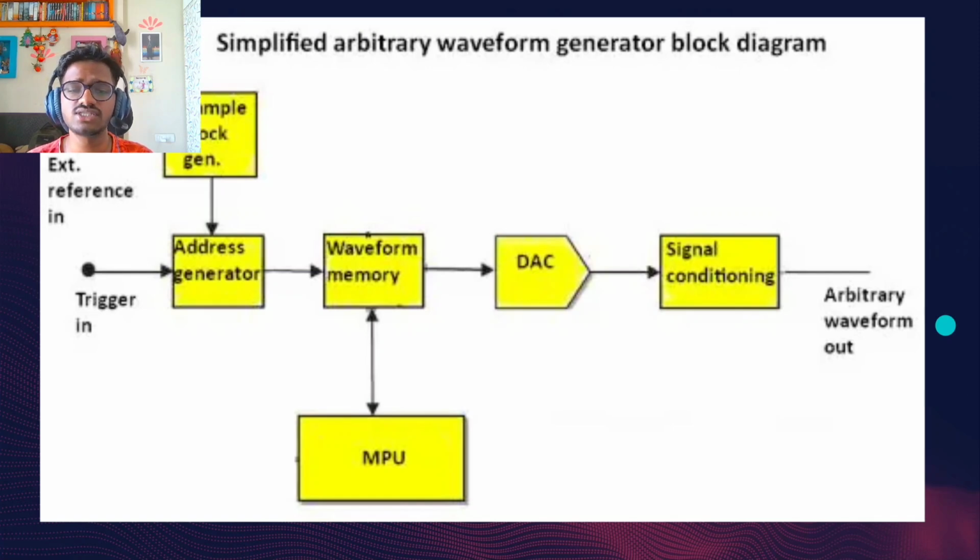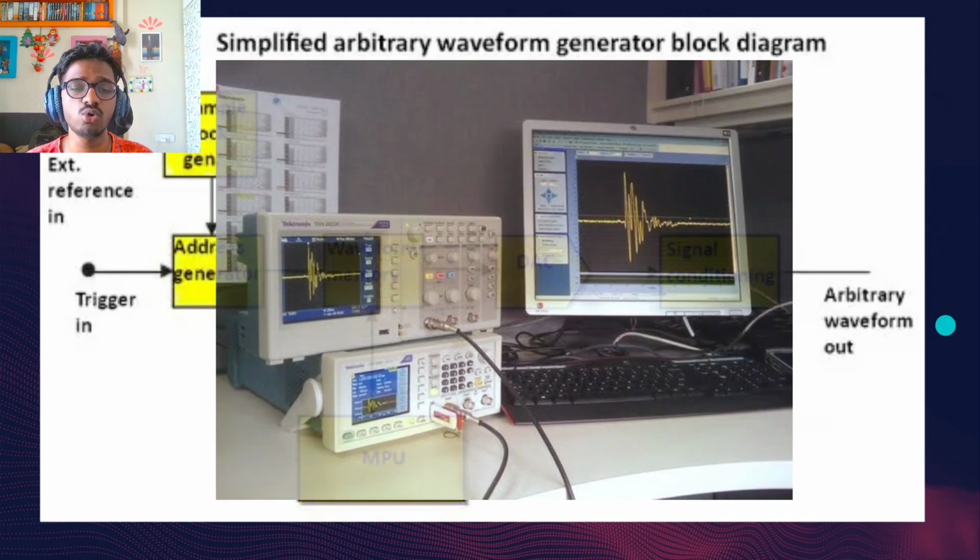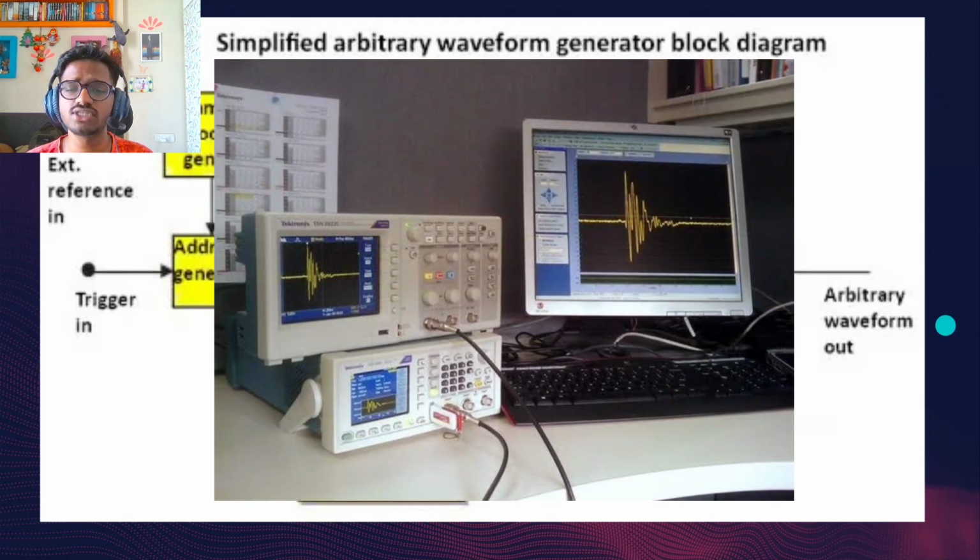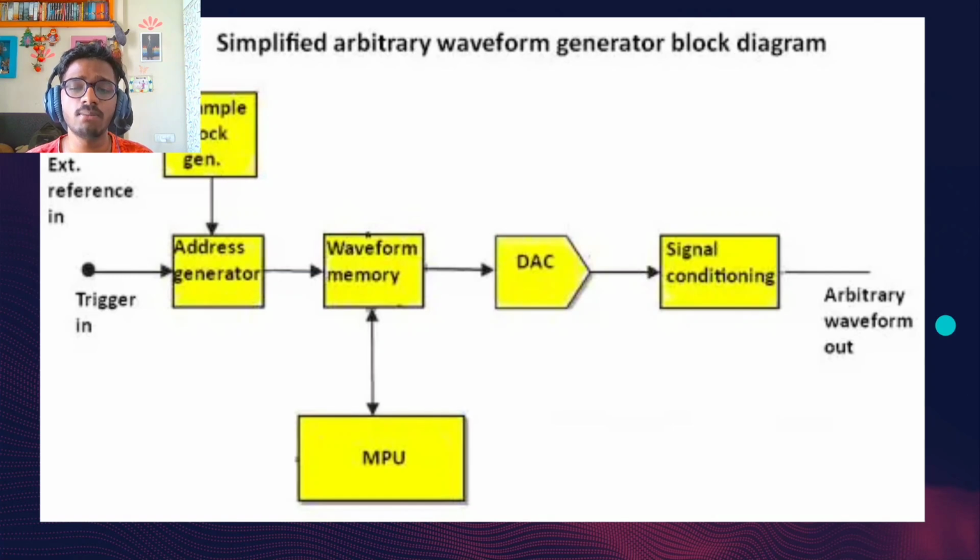While MATLAB and signal processing toolbox are common for signal generation, AFGs now feature a plugin architecture for easier waveform creation. These plugins, integrated into the AFG's GUI or run on a PC, accelerate the process of generating signals for specific applications or simulating real-world environments. Plugins cover areas such as generic precompensation, high-speed serial, multitone and chirp, and optical signals. Some common plugin capabilities include generic precompensation, simple generation correction features for cleaner signals and lower error vector magnitudes.